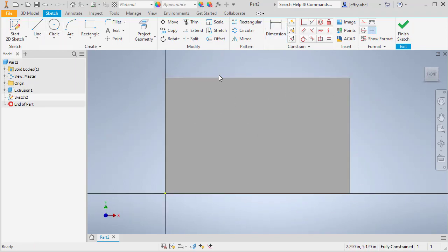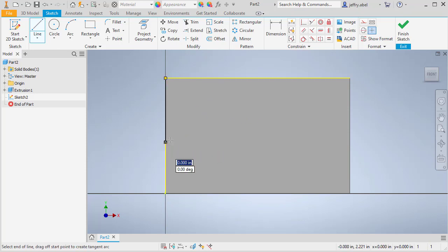And now I want to cut off these upper corners. So I'm going to draw in some triangles. I'm going to go from this top corner, making sure that it is coincident, come down, make sure I'm on that line, and then go from this point up here and there to there. So now I've got that triangle there. It doesn't have the right dimensions, and since I'm locked to this corner point, you can see these 2 lines are black, which means that they're defined. This one is not defined, so we need to add a couple of dimensions in here.